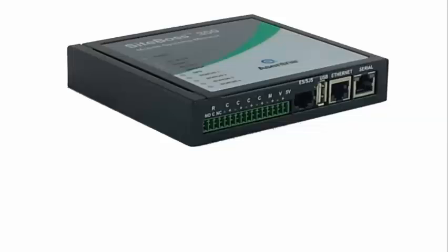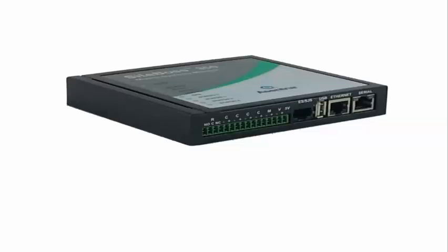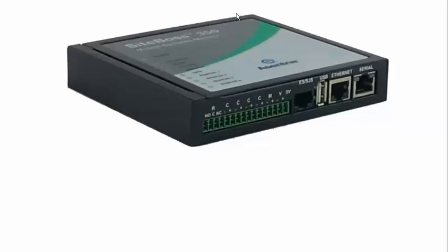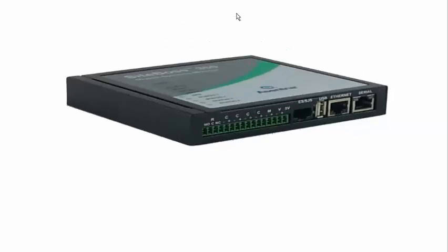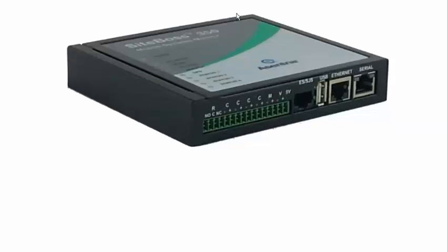The backside of the 350 holds an input power jack and two RF antenna connections for the cell and GPS antennas. The 350 runs on 10 to 28 volts DC and can run in a 48 volt environment with an additional power converter. The 350 has a highly optimized sleep mode, which allows it to wake up frequently or occasionally to check in with the network center and to send its GPS coordinates, allowing the 350 to cause only a minimal drain on a generator battery. If the generator or the vehicle moves, an internal accelerometer can wake up the 350 so it can send immediate notice and coordinates to the network center.